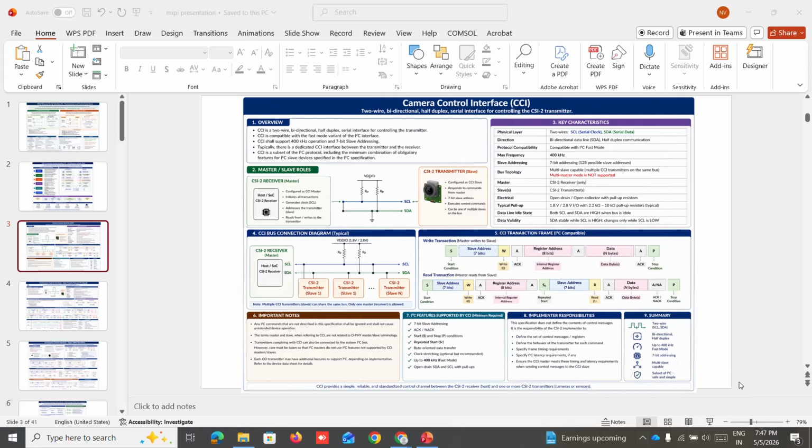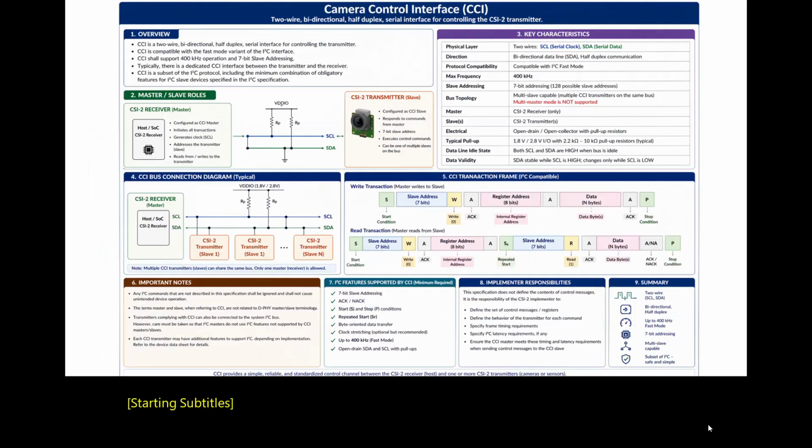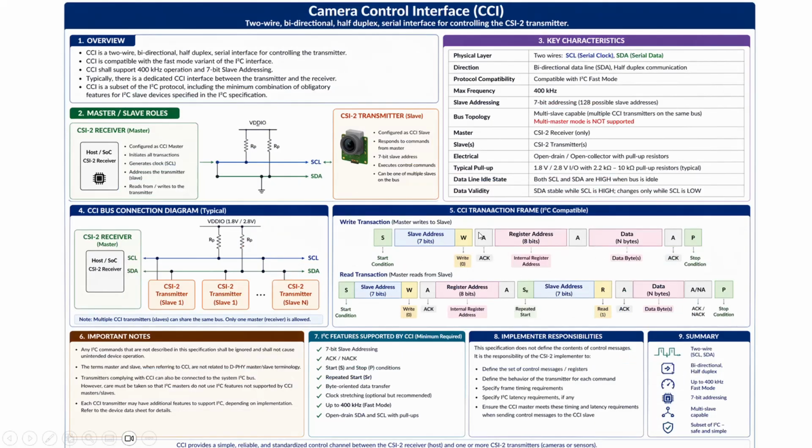See how the transmission will happen, means writing the data and then reading the data. While writing the data, we are putting the start condition, then the address, and then the write bit along with the address. And then we also keep the acknowledgement. After keeping the address, we need to get the acknowledgement bit from the slave, and also the register address.